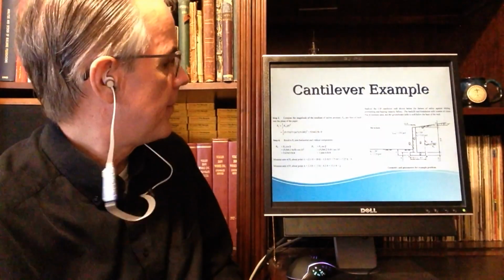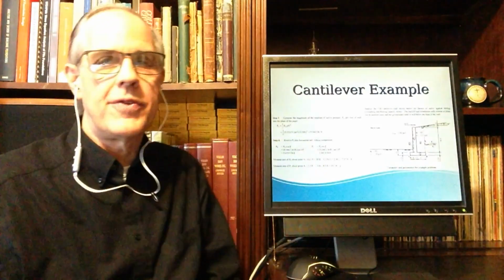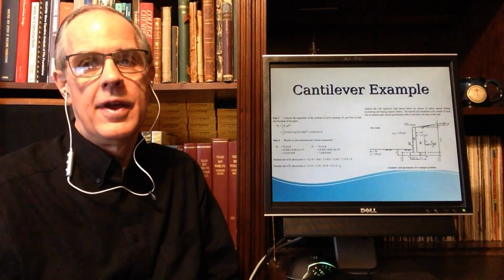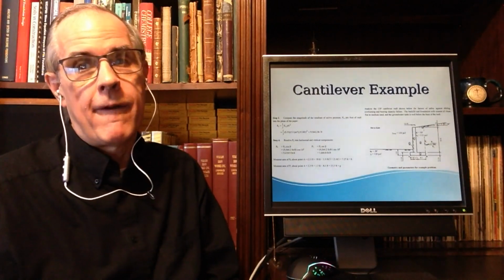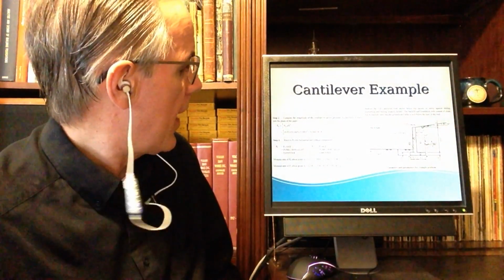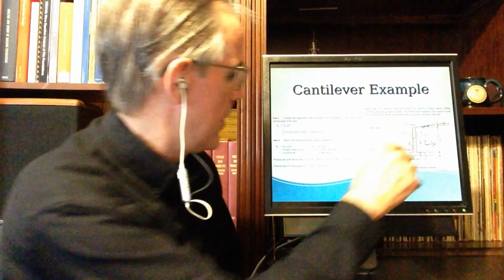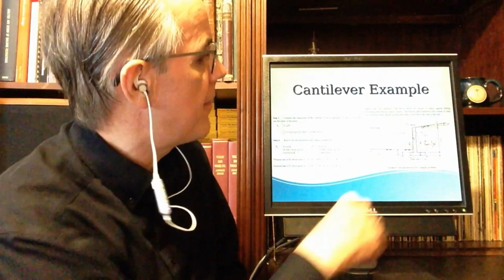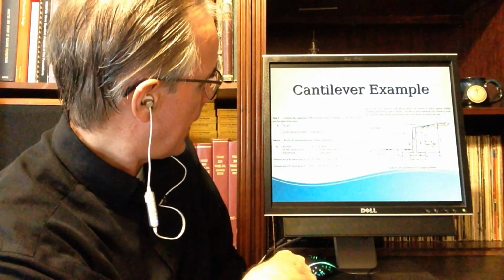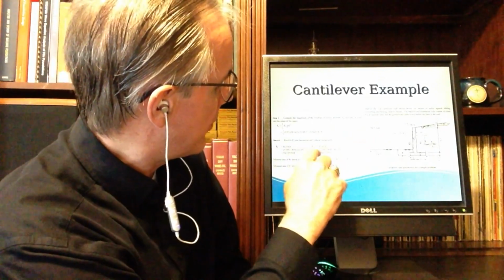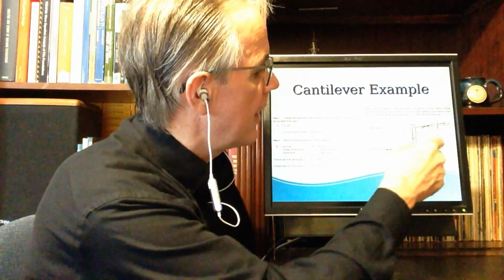Either way is fine. The only thing you would have to do is instead of having 115 PCF, you would have 0.115 KCF, which you see in some military documents. You don't see it very often anywhere else. So we'll continue on. All right. Step 4, resolve PA into horizontal and vertical components, using the cosine of beta and sine of beta, beta being the backfill angle. We resolve those into two components because this force, because of the backfill, acts at an angle.